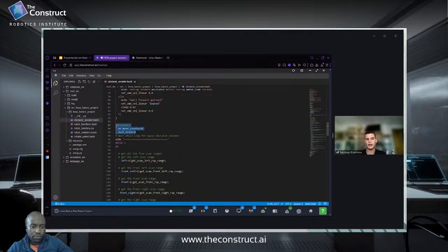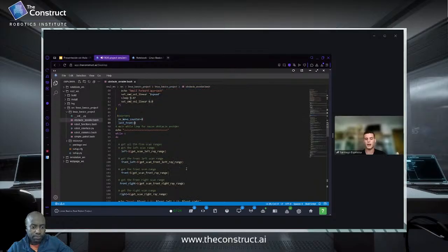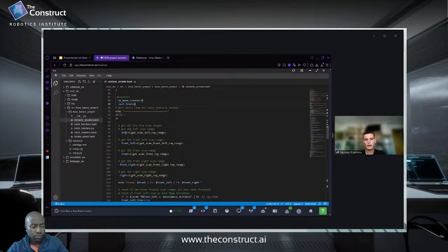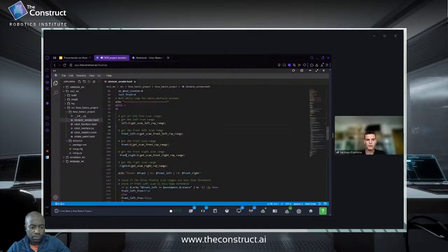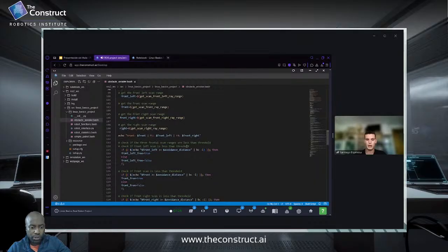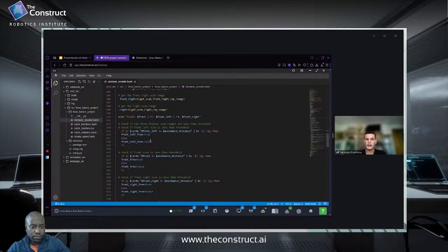These are a counter for what I did in the function in case it gets stuck, if during 5 loops it has the same values. What I said before, it never happens, but I did it like that. Put it on 0, and then I keep adding 1 in these cases, and when it's 5, I return them to 0. Now here in the while, I call all the getters. Left, front. I show on the screen front, front left, and front right, which are the most important to do all the functions. And I define when they are free.